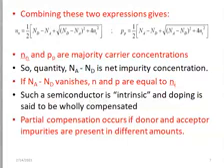Now, this Nn and Pp are the majority charge carriers: Nn electrons and Pp holes. So the quantity Na minus Nd is what we call the net impurity concentration. That is, if you take Na, the concentration of the acceptors, minus the concentration of donors, it will give you the net impurity concentration. So in a situation where Na minus Nd is equal to 0, where it vanishes, you find that N and P are equal to Ni, the intrinsic concentration.